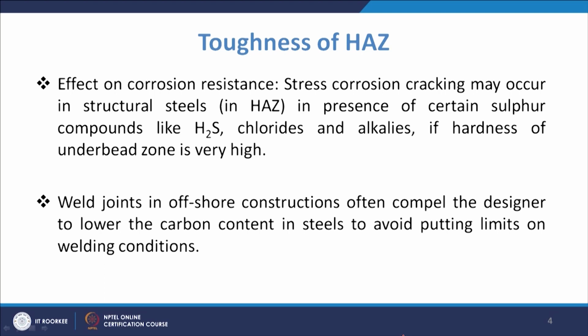It's not easy to predict that toughness in that underbead zone. Now, the other aspect of this toughness of HAZ. Now there are other properties also, not about the toughness. Basically, it is about the other effect on other properties, that is your stress corrosion cracking.